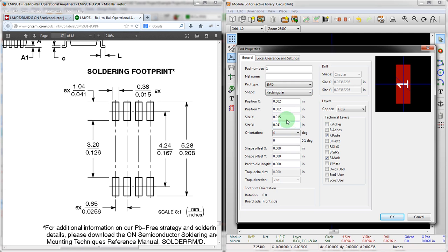All right. As we go down here, orientation's fine, offset's fine, pad length is fine. These aren't options for us. There's no drill here. That would happen if we switched over to a through hole, so we don't have to worry about that. And then we look at the layers here. So we're going to put on the top copper. We're going to also have paste setting on the same thing, and then solder mask setting, which is actually solder mask relief. So each time we put down a new pad, there will be a copper layer, a paste layer, and then a solder mask layer.